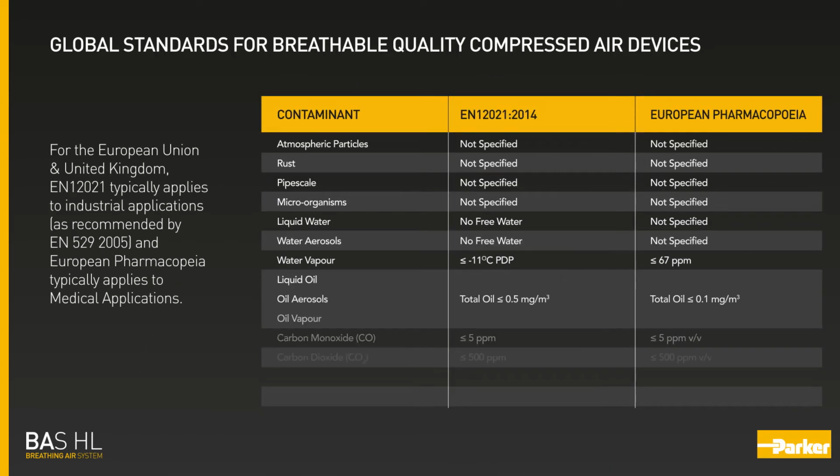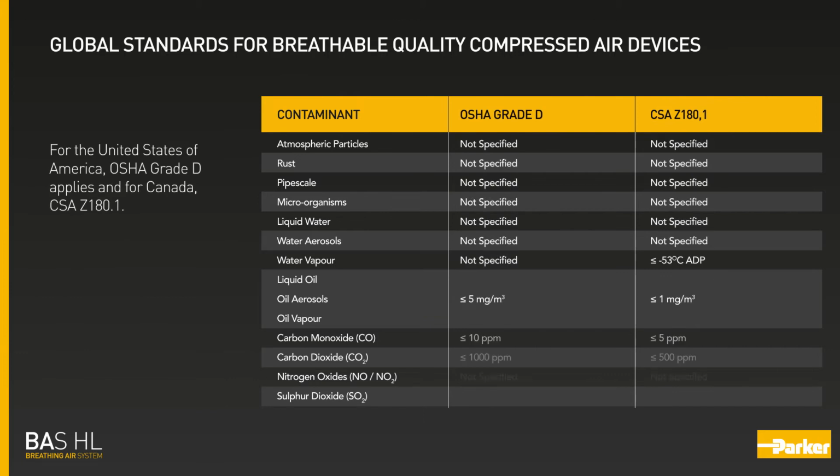For the European Union and United Kingdom, EN 12021 typically applies to industrial applications, as recommended by EN 529/2005, and European Pharmacopoeia typically applies to medical applications. For the United States of America, OSHA Grade D applies, and for Canada, CSA Z180.1.